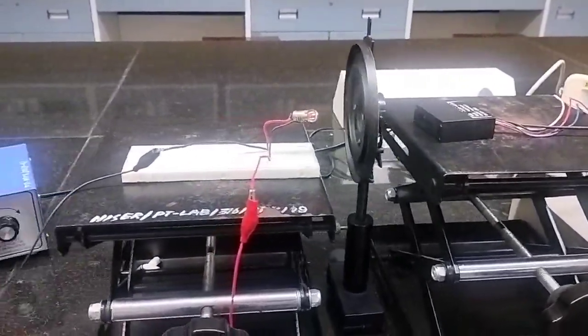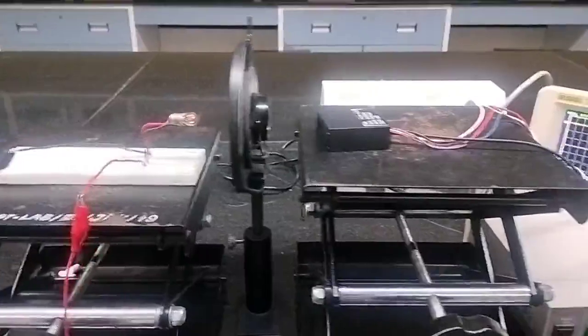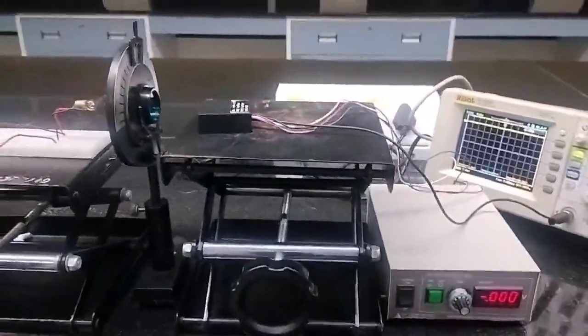To study the gain of the PMT, the control voltage varies from 0.3 volts onwards in steps. Now we are varying the control voltage, starting from 0.3 volt. In between we have to keep 0.3 to 0.5 volt to fix the control voltage.